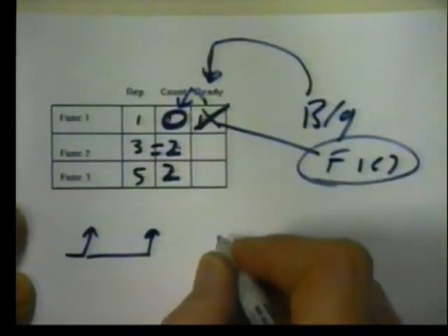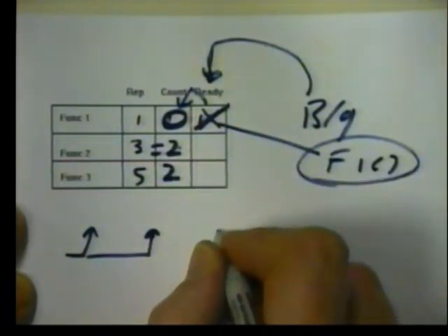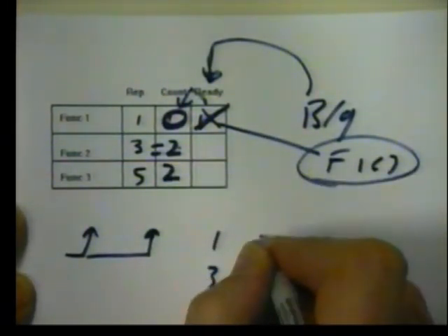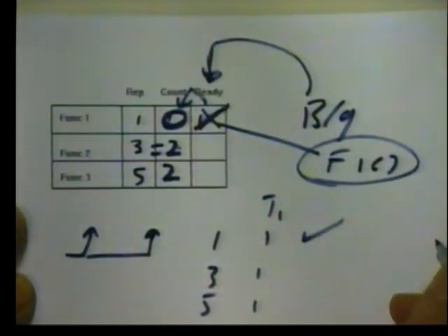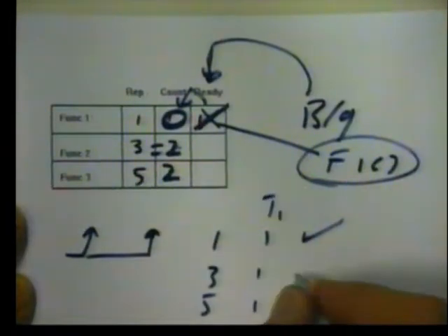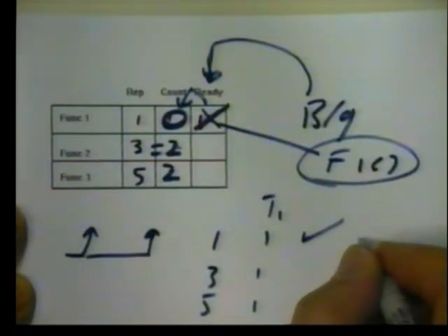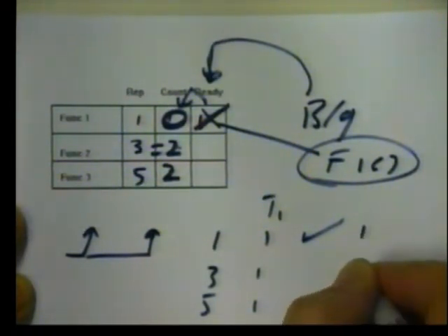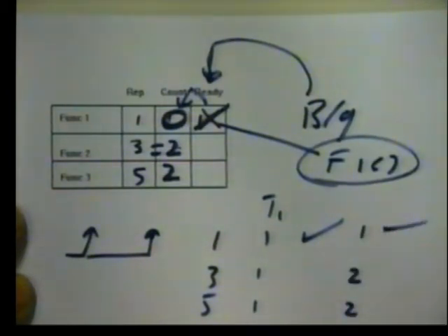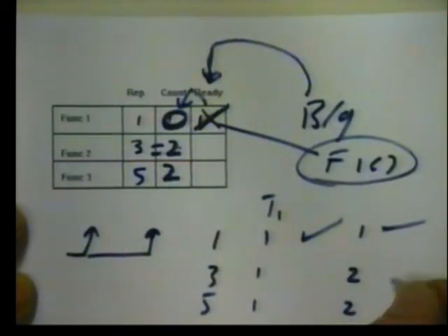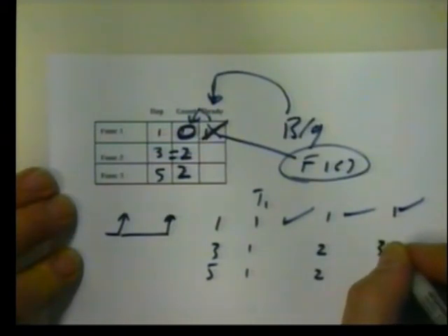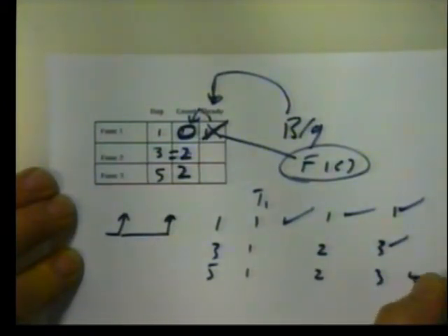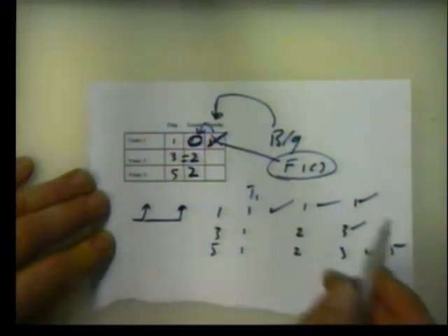Because what would be happening in time, if you looked at the count fields, we would go 1, 3, 5, we go 1, 1, 1 would be at time slot 1. That would be signaled to run, so it would happen every 100 milliseconds. Next time round, we'd get 1, 2, 2, so that's signaled to run again every 100 milliseconds, but not these. Then we'd get 1, 3, 3. That runs and that runs, but not that one. That one will not run until it equals 5.